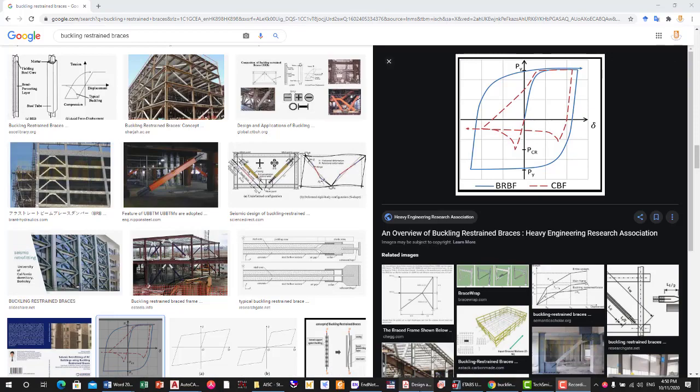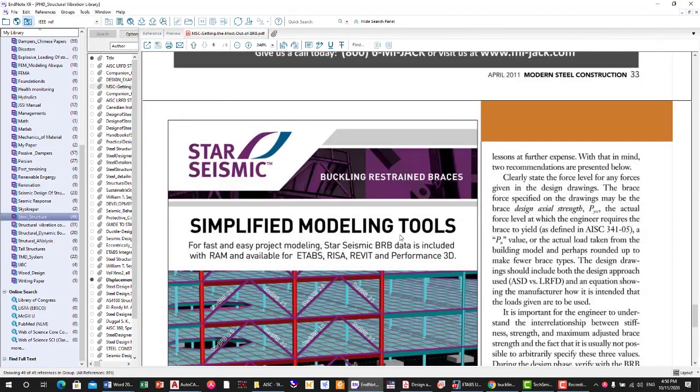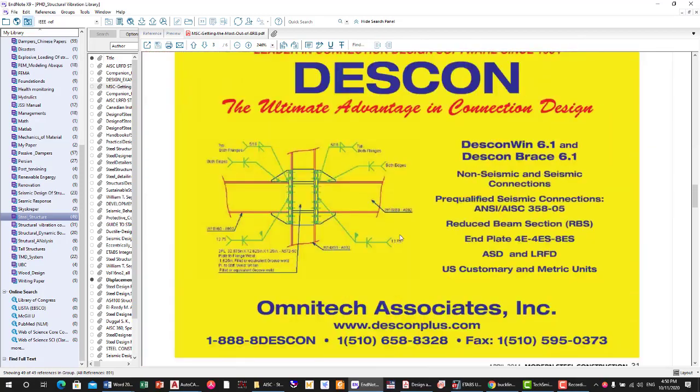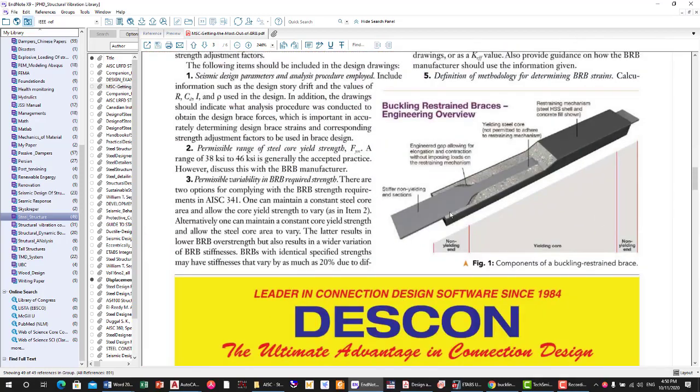The only way is to provide a sort of method which can prevent this buckling. So this is a BRB which has a core steel and unbonded concrete. The main point is the steel should yield, for which we have to provide a very low strength steel, and the remaining part should be stable to resist the compression load.